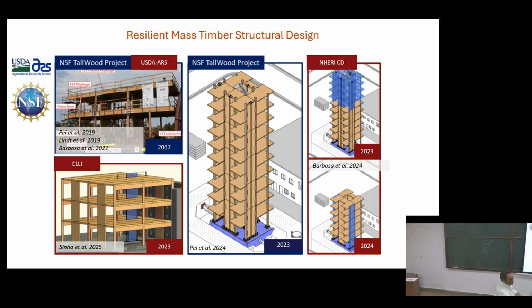There were screws as reinforcement, and then the concrete was poured on top of timber. That was one of the projects that we did, and that work led to a lot of different code changes on the timber concrete diaphragm and design guides for that.